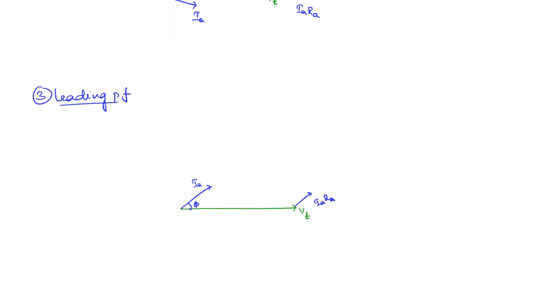Now what will be the drop across the reactance? Synchronous reactance, this will be 90 degrees leading the current phasor. So that means it will appear here. So this is what you are going to get. J times IAXS. Okay. So now what will be the generated voltage EG? It is going to be like this. So you can see that this generated voltage can in fact be lesser than the terminal voltage if the right conditions are present. Okay. So these are the phasor diagrams for various power factors of the load.